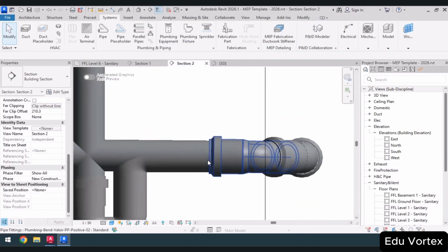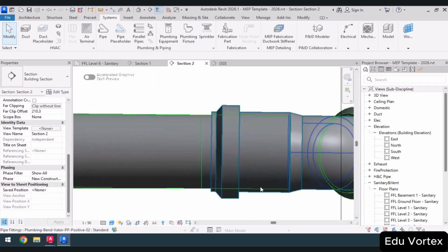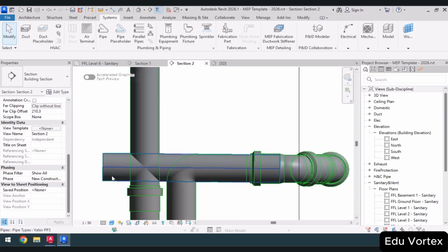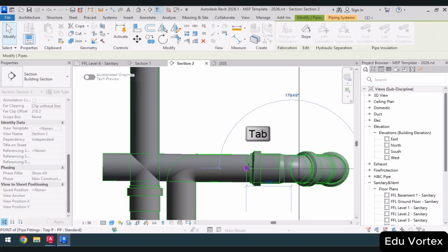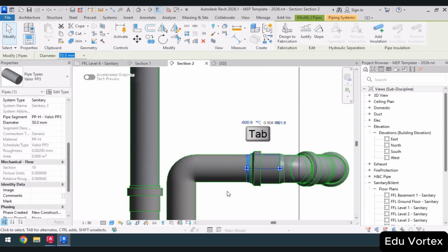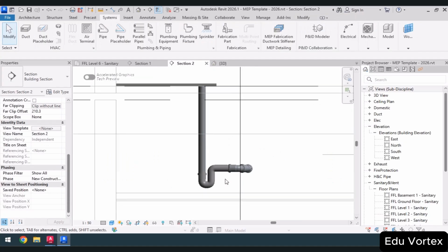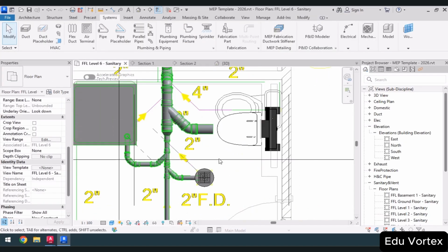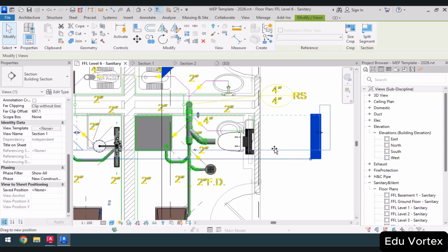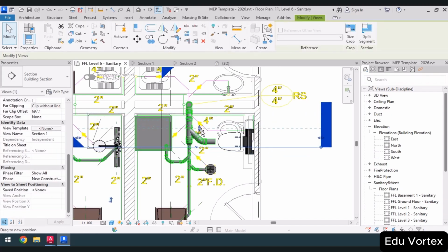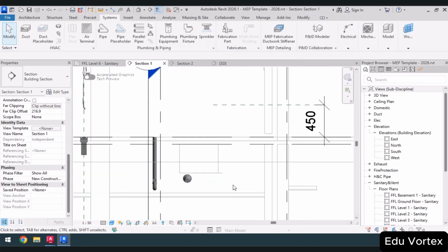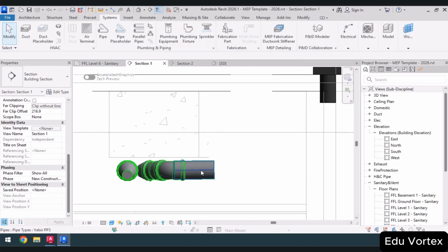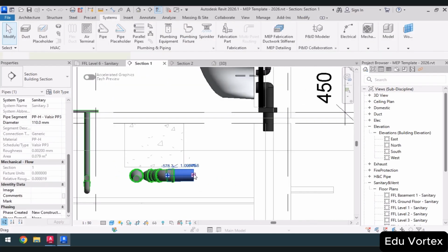So returning to the section view, you can see that a gap has been created between them. So I will drag this pipe and use the top key to connect it to the edge of the siphon. This way we have established a connection in the section that aligns with this pipe. I will compress it a bit. I will right click and go to view. You can see that this is our BIM and the pipe has been passed under it.